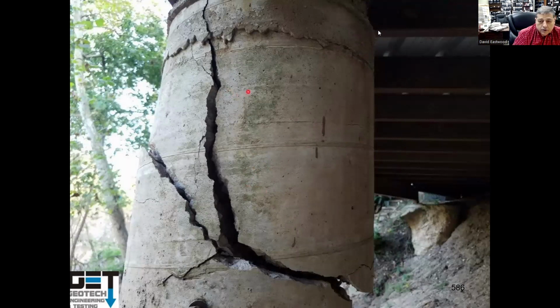A large volume neighborhood water well is located within a few hundred yards of homes. Can this contribute to settlements? Yeah, water wells can cause what's called subsidence, which is a form of settlement. As you take the water out, you increase the effective stress in the soil, and the area starts settling. Understand the aquifer is limestone in South Austin. Houses have a lot of movement with cracks. One house has exterior piers and has seen movements in the cracks. Anyway, wells with a large volume of water cause shrinkage. Basically, this is subsidence and settlement of the ground around it.